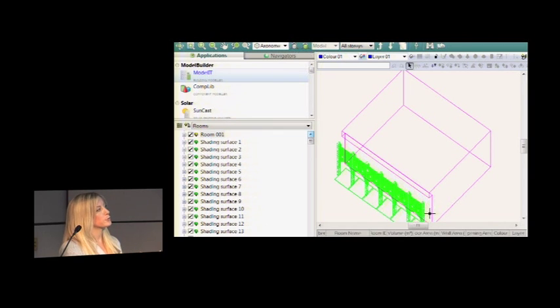So there may be points where if you do want to actually look at a small part of a facade or a small portion of a building and see how it performs, you can actually section it off and use it that way. So you may use a portion of a model, or you may use a section of it. I've had extremely huge models that you just break into pieces and say, I'm going to use this part or that part. In the same way that you may pull out a laboratory and use that for a CFD analysis. Simple room by itself, not the entire building.